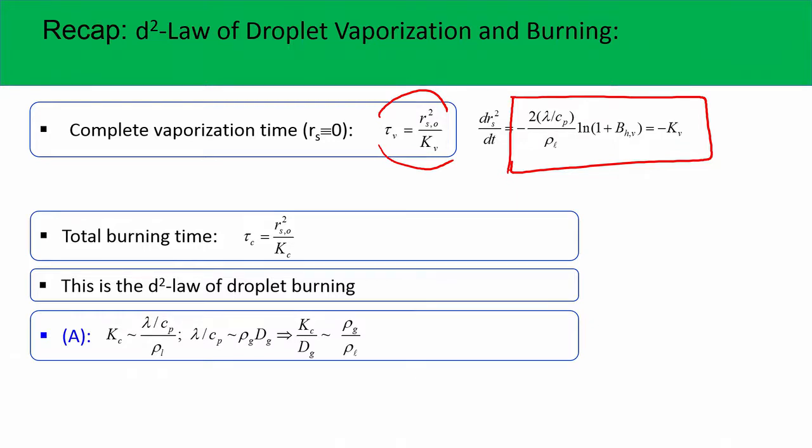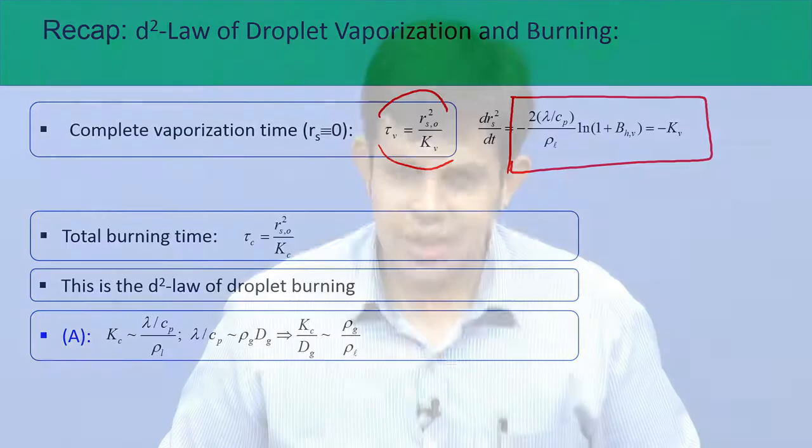So a very important function of the liquid injector inside a gas turbine combustor is to produce droplets of very, very small size. The ultimate product is that I will take the liquid, connect this injector to my liquid tank in some manner, and make some arrangements so that this injector can spray and send out these liquids, and they can create a mist of very, very small droplets. Okay. But how does that happen?